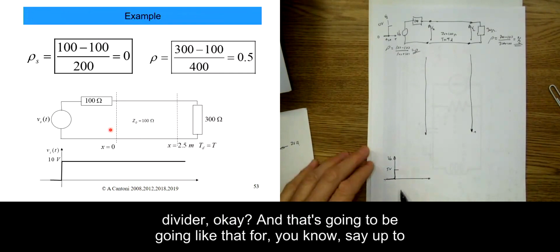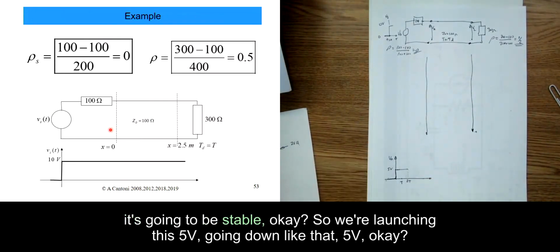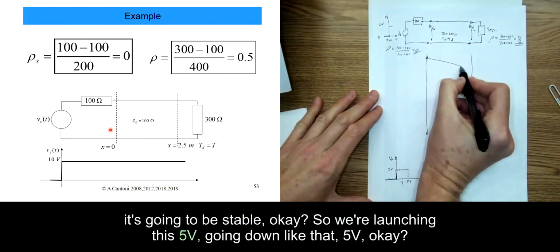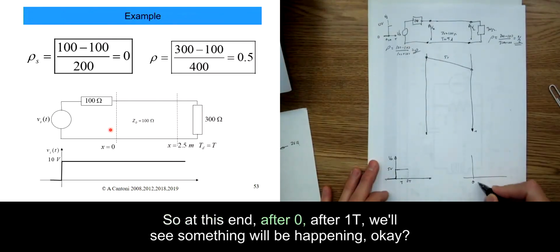And that's going to be going like that for, say, up to T until something comes back from the other side, okay? So at least the 2T is going to be stable, okay? Yeah, so we're launching this, 5 volts. It's going down like that, 5 volts, okay? So at this end, after 1T, we'll see something happening, okay?